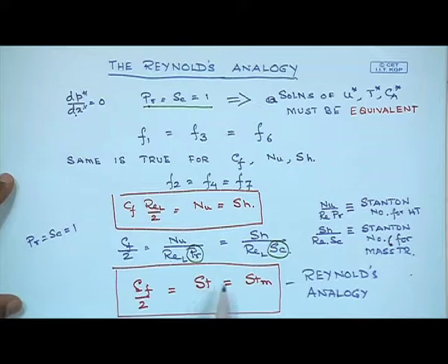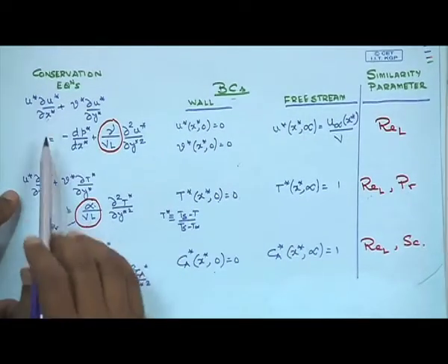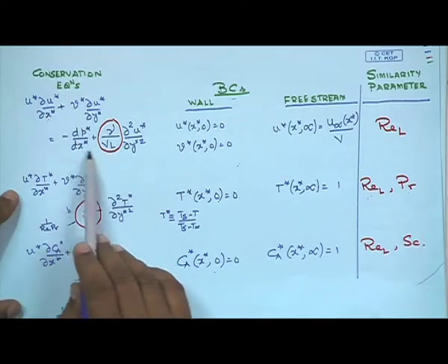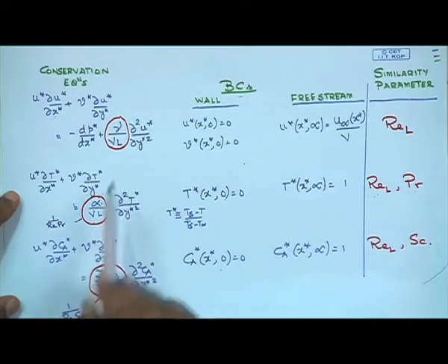the heat transfer and the mass transfer are coupled to the hydrodynamic boundary layer, but the equation of the hydrodynamic boundary layer is not coupled with the temperature or with the concentration as long as the properties remain constant. Which would be even more clear if you look at this expression once again. Here I have the velocity, but nowhere in this expression either the temperature or the concentration appear.